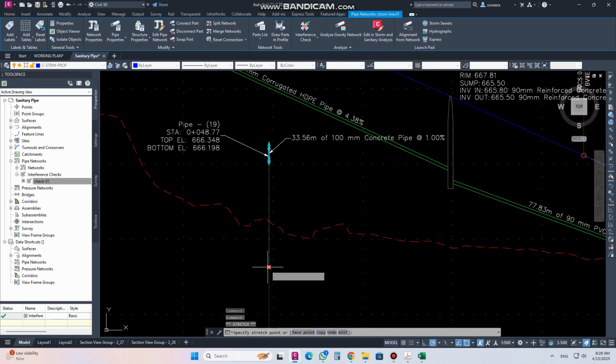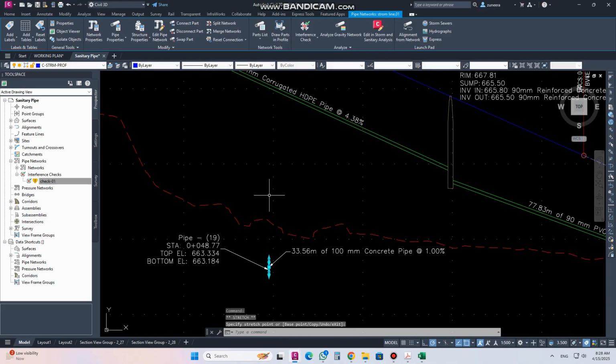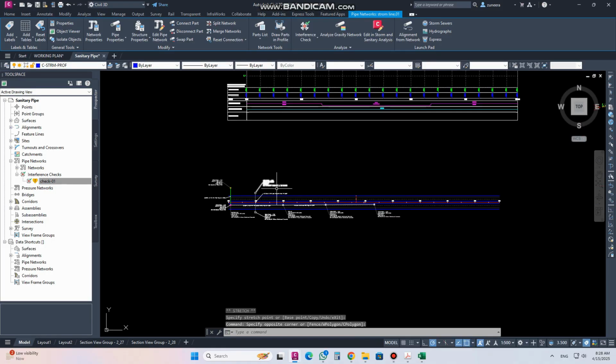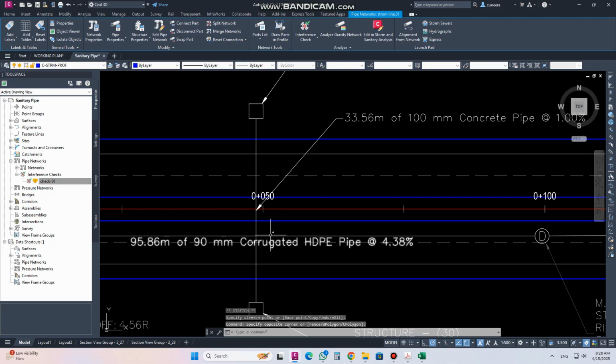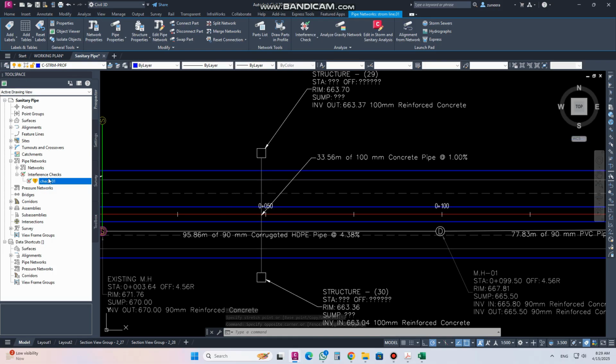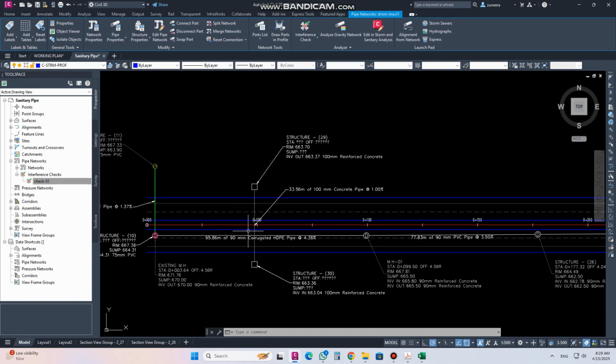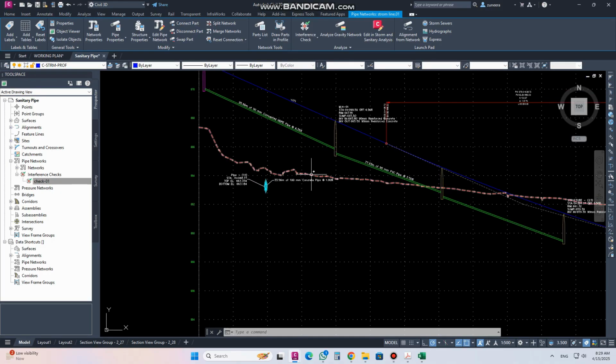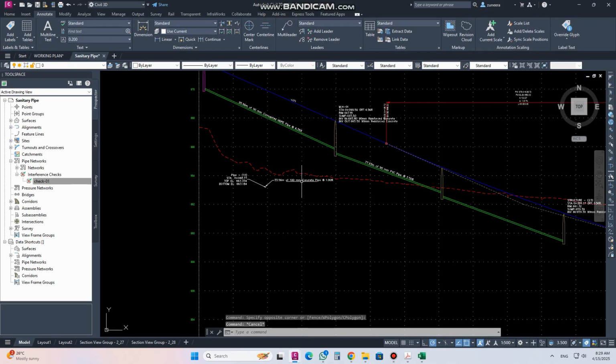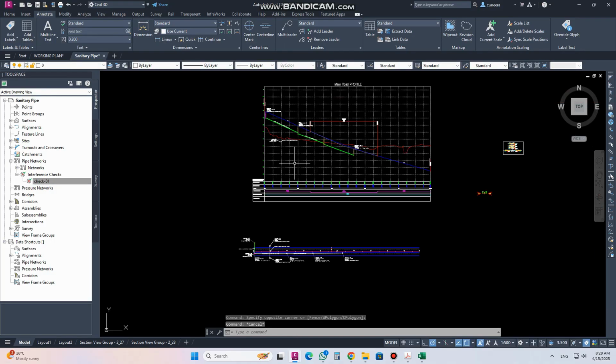It will show if there are. Just move this down again here, and now I will zoom this line here. Now as you can see, I rerun, and this says 0, it has moved. So like this you can check the interference if they are intersecting each other.